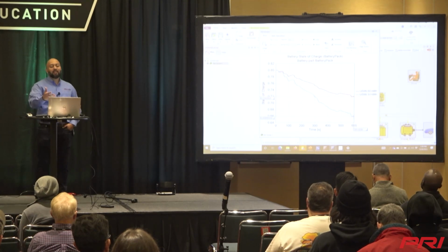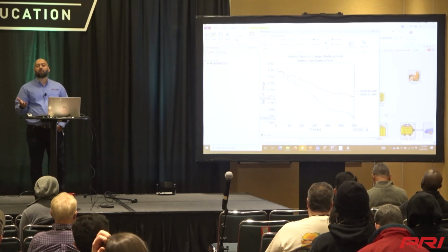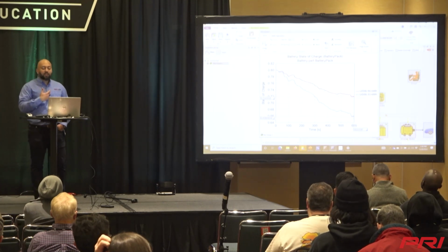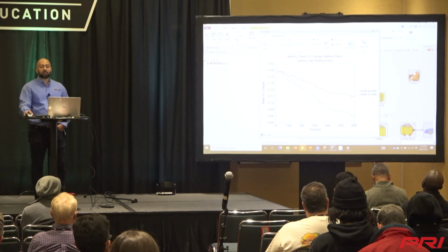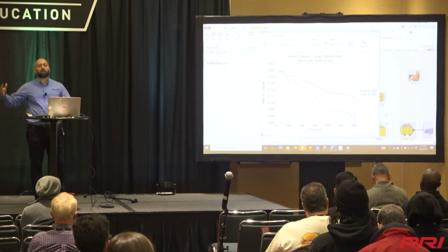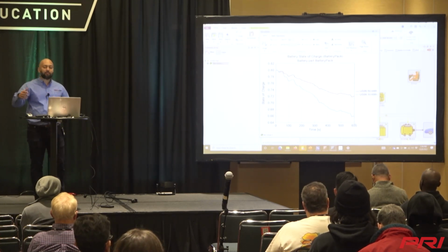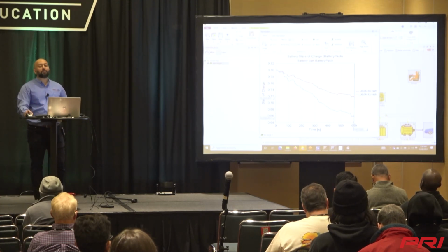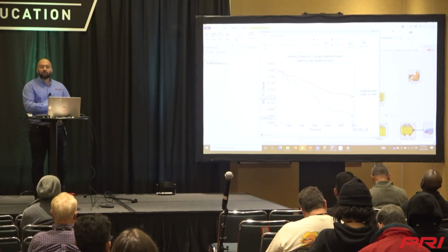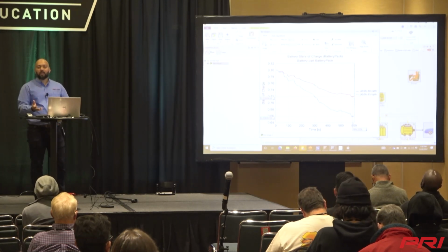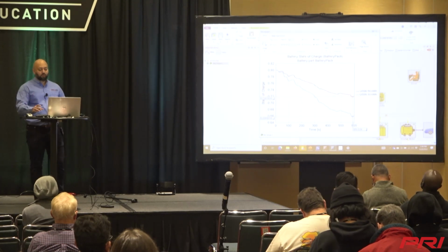Now you might say that, okay, this is not bad. I can make use of a 33 kilowatt hour battery. Now we are using a US06 drive cycle, which is 600 seconds. Imagine if you have a longer drive cycle, or you are running laps of a particular drive cycle, you will be able to use this information to determine this car is going to run X laps based on the battery size I have. And that can determine which battery you use.